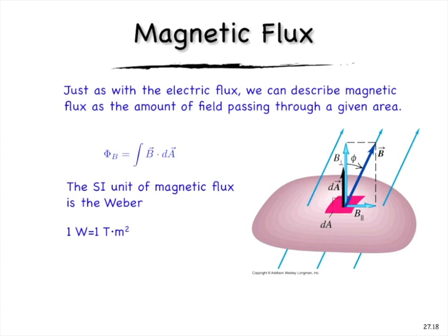There are some tricks you can play with the magnetic field. Magnetic field tends to be guided by ferrous metals, by metals that have a lot of iron in them. And so if you take an iron rod or an iron, whatever shape that is, that's a loop of sorts, and you put the coil around that, when you put current through the coil, you've produced a magnetic field that goes through the axis of that coil, like we just showed.